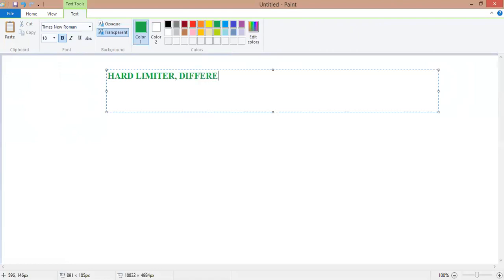Not exactly a differentiator from the beginning, because the signal may vary in amplitude due to some undesired component added from the channel. That is why I need to pass it through a hard limiter to bound its amplitude. How to do that, I will show you. After that, you need your rectifier or envelope detector.